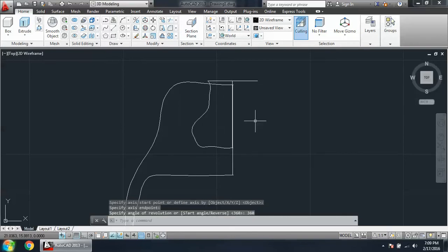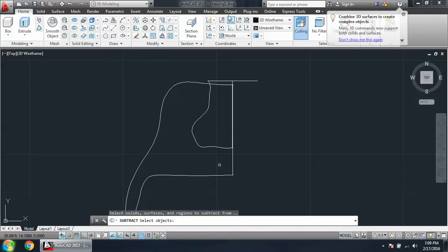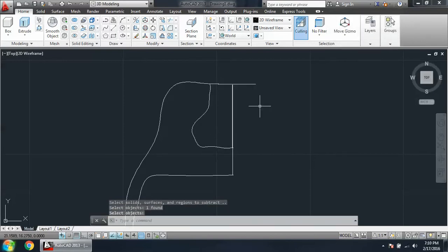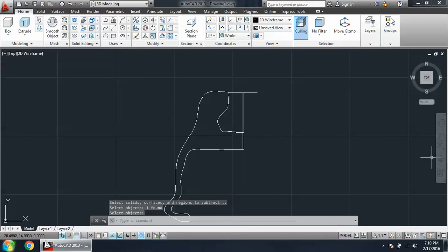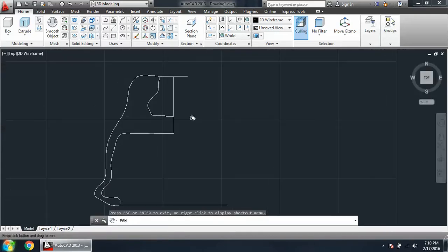So in order to make the hollow space, we have to remove this solid portion from the external disk. So what we do is that we type the subtract command, we select the whole disk, whole top, and from this we remove this portion because it's solid. Now it's done. Also, as we know, a portion of one side of this top is open while the other side is closed.